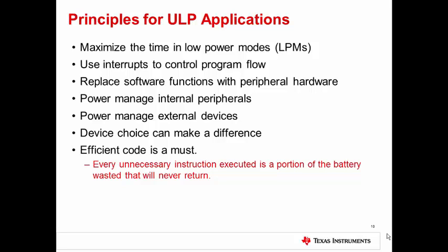Device choice can make a difference. More memory or a bigger device can consume more power. Some technologies, such as FRAM, can reduce power consumption significantly. And overall, write efficient code to avoid unnecessary cycles.